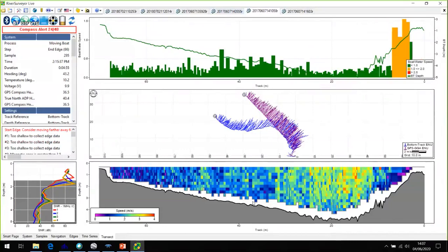There's not much bed movement in the first half of the river because the blue overlays the purple. But then there's a strong apparent movement upstream of the blue line. And then it gets slower again towards the far bank as the angle becomes closer to the true angle as reported by the purple.